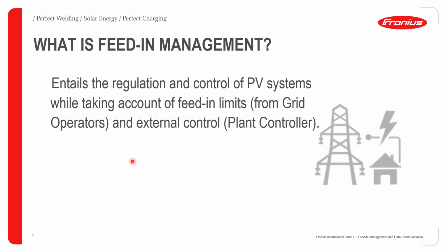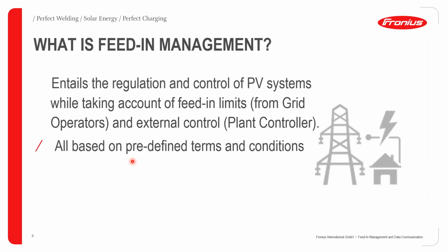One could basically say that it entails the regulation and control of PV systems while taking into account the feed-in limits that are usually provided from the grid operators and of course external control components, which usually in most cases are comprised of a plant controller. All these are based on predefined terms and conditions that are usually specified by the grid operator.